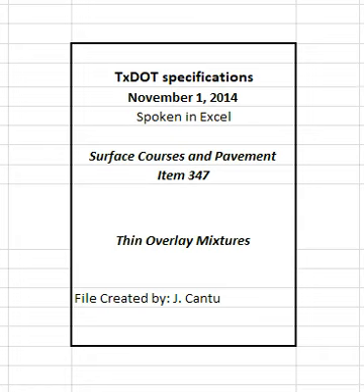The engineer may perform tests at any time during production, when the contractor blends Class A and B aggregates to meet a Class A requirement, to ensure that at least 50% by weight, or volume if required, of the material retained on the number 8 sieve comes from the Class A aggregate source. The engineer will use the department's mix design template, when electing to verify conformance, to calculate the percent of Class A aggregate retained on the number 8 sieve by inputting the bin percentages shown from readouts in the control room at the time of production and stockpile gradations measured at the time of production.